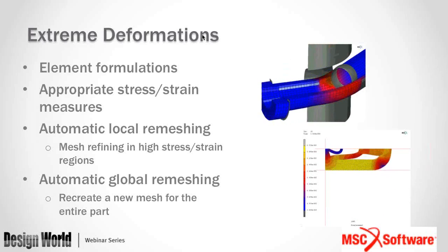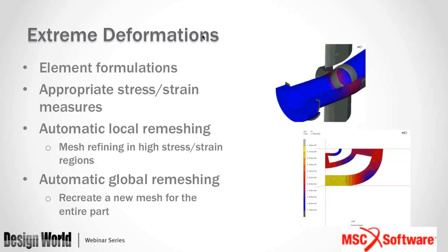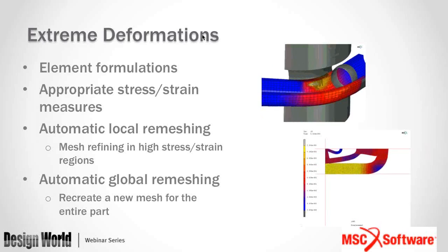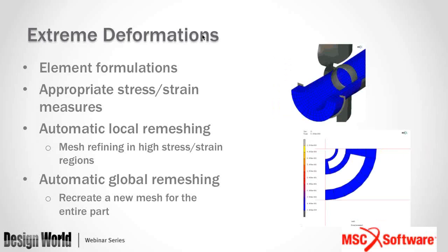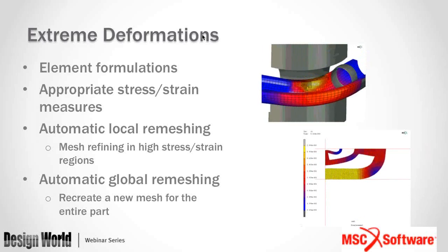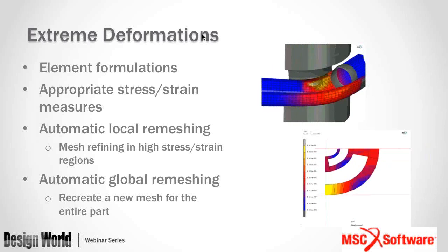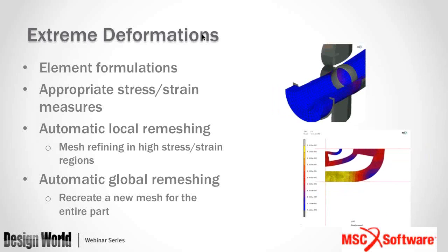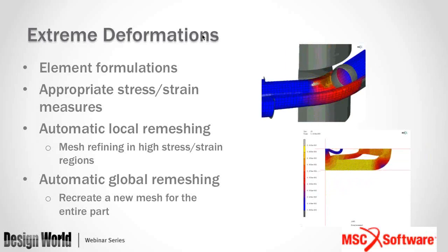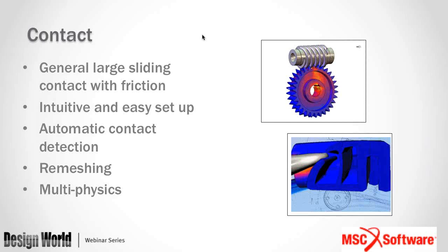And of course, the prior state of the structure, including all the stresses and strains and also deformations and temperatures, are all mapped onto the new mesh so that you don't lose this vital information. Here in the animation at the bottom, that is what you see. You can see that the mesh is getting updated as the structure is getting deformed. I'm showing a simpler example there, but you can also do the same thing for 3D models as well.